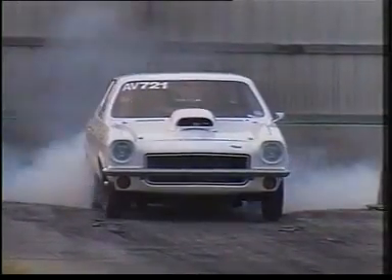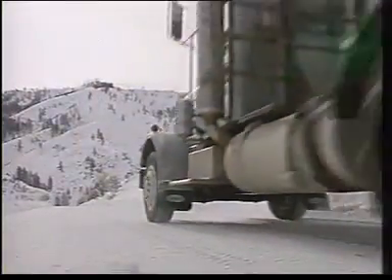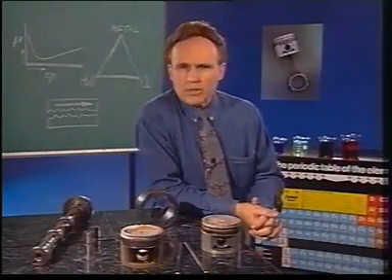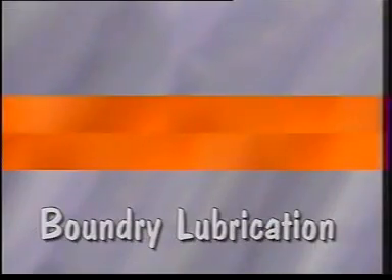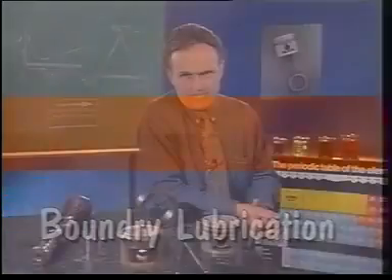Fluid film lubrication fails, however, under shock loading, low speed, high torque operation, or low lubricant viscosity. Under these conditions, the machine operates in what is called boundary lubrication, and wear is prevented by using extreme pressure anti-wear additives in the lubricant.